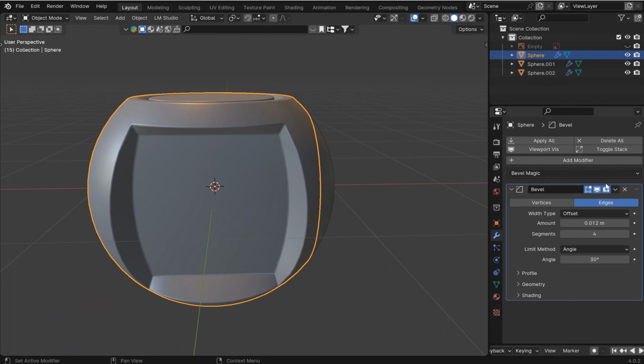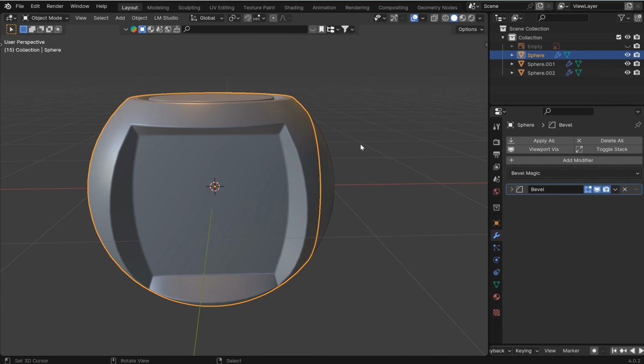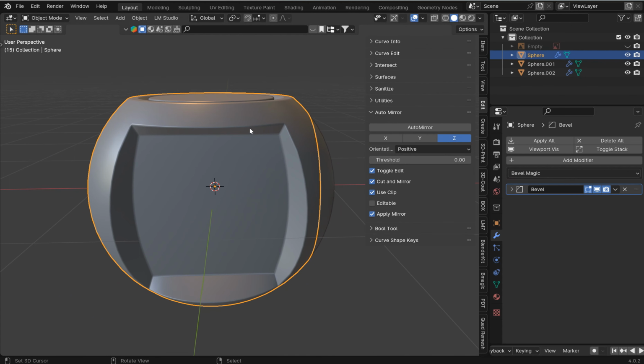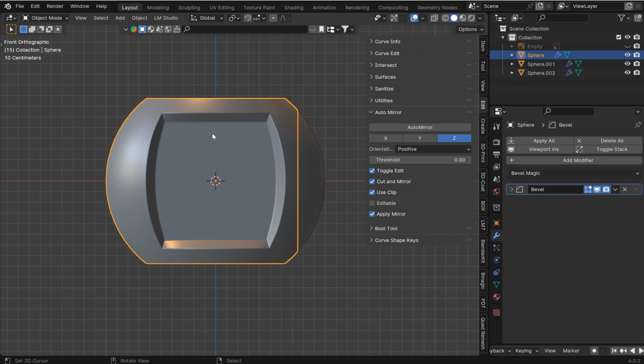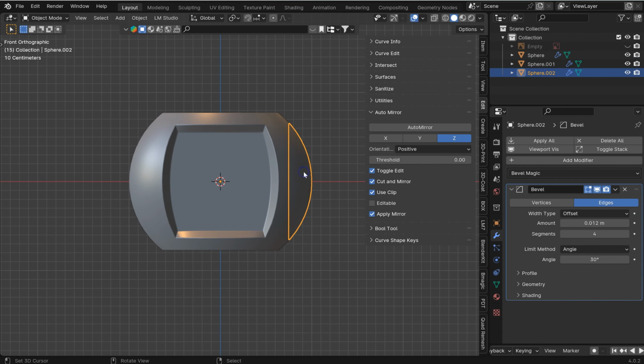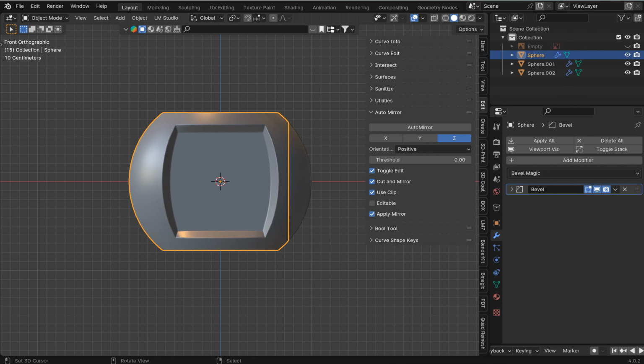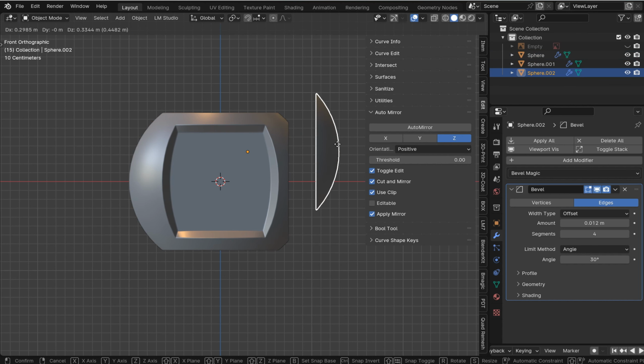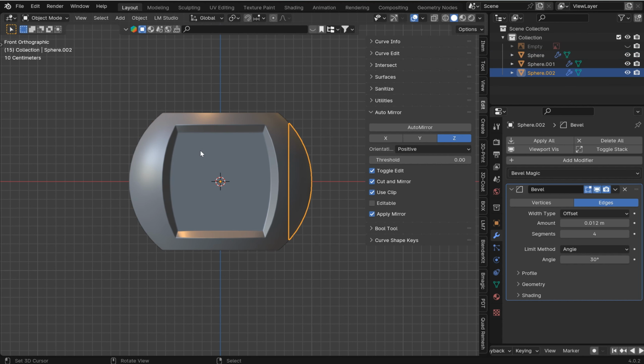There's two things you've got to do for this. This is a little bit more tricky, but if we come over to the auto mirror, take up the orthographic front view. I'm just pressing 1 to get there. What I want to do is mirror the main object, and then I've got to actually mirror the piece, because this is an individual piece that now has to be mirrored, and it's got its own origin, which is the original geometry's origin. So if you reset the origin on this, it's not going to end up in the right place. So you could just frankly leave it where it is.